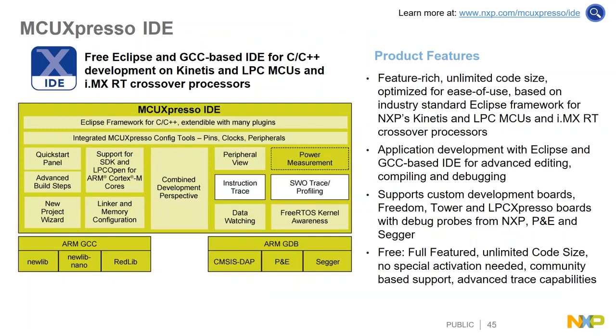That's when I wanted to implement this slide in this presentation, because the MCUXpresso is free, full feature, unlimited code size. You can use it not only for the LPC devices, you can also leverage it for Kinetis and i.MX RT. So across the microcontroller line here on nxp.com, you can use it. If you're familiar with Eclipse or GCC-based IDEs, that's perfect, because this is based on that. It's application development with the Eclipse and GCC-based IDE for advanced editing, compiling, and debugging.